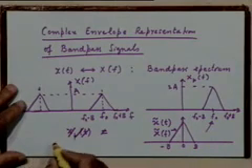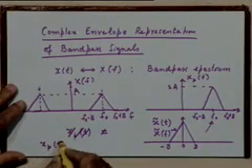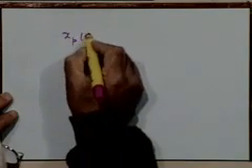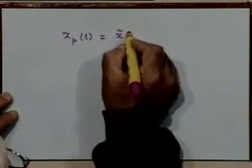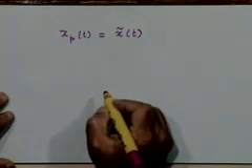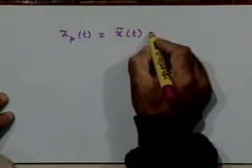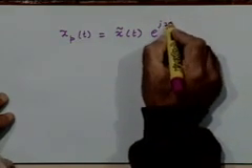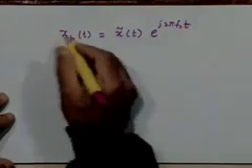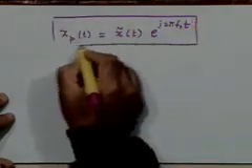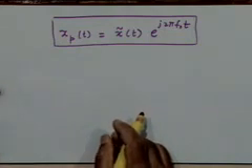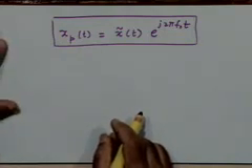So you can think of xpt, maybe I should use the next page, as a frequency translated version of a low pass signal, complex valued low pass signal x tilde t, so that xpt is equal to x tilde t e to the power j2 pi f naught t. Now that's a very interesting way of looking at it, right? You have already done half the job.